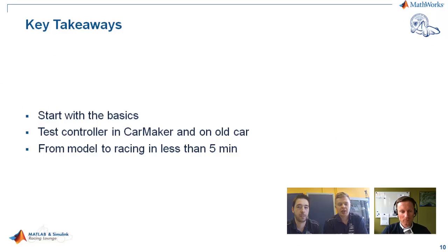Yeah, so finally, the biggest advice that we can give to any team out there is just start with the basics. There's no need to get yourself drowned in all the little things that can maybe influence the car. Just start with a simple 2-track model or 1-track model. Yeah. And it really is about 95 to 98% of the performance that you want.